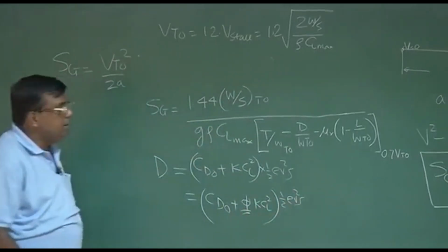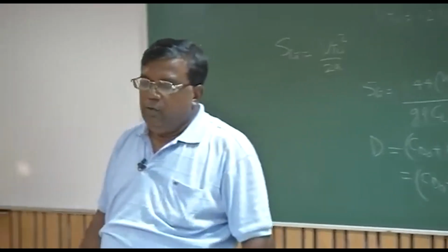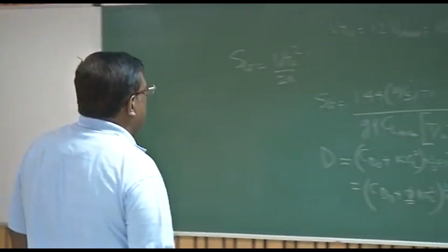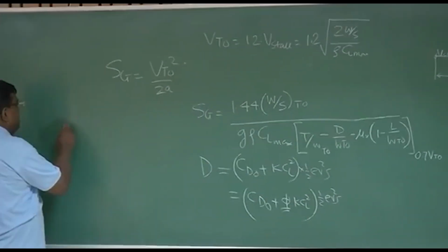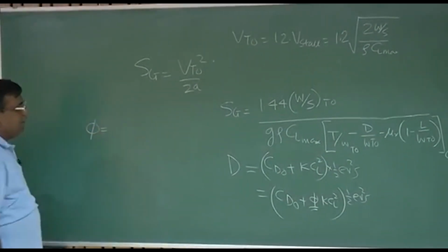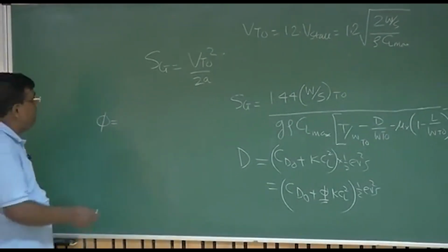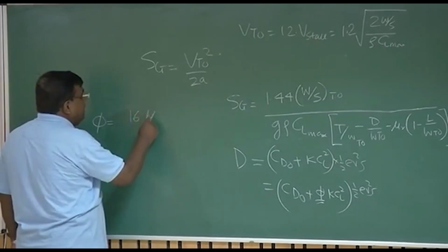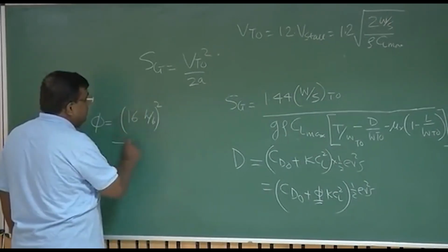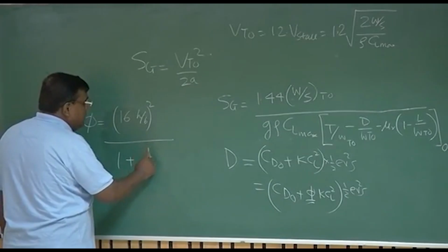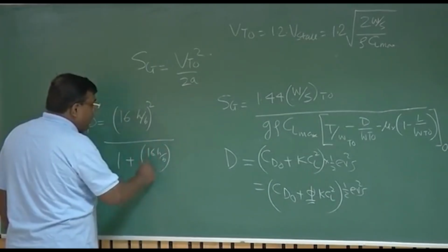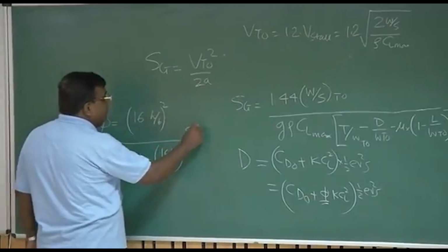So this phi, number wise, if you take, induced drag is around 70 to 80%, good enough. That means 20 to 30% reduction is there. Okay, 20% is a fairly good initial design approximation, but many researchers have made efforts to give an expression to estimate phi for incompressible flow, and that is modeled as (16h by b) whole square divided by 1 plus (16h by b) whole square, and this value is less than 1. I will explain what this is.